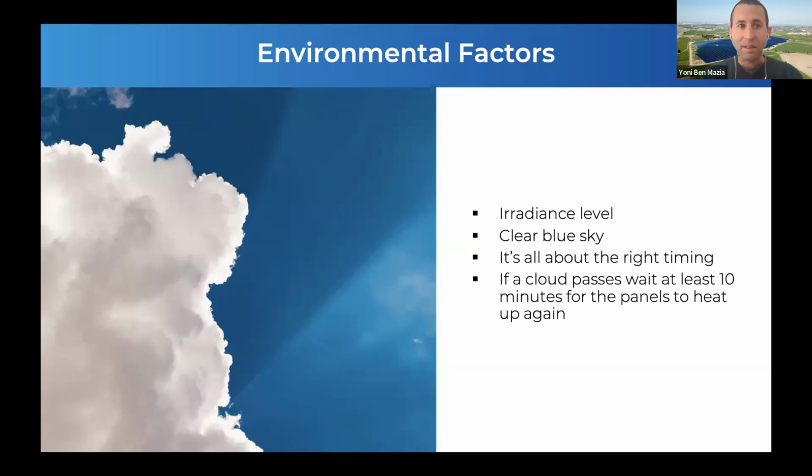And there are some coincidences: the pilot comes to the site, starts to fly, and then a cloud comes in. So usually the instruction is, when we have shade on the system itself, land, wait for the cloud to pass by, wait a few minutes for the modules to start producing again and heat up, and then resume the flight from the point where you stopped. But this is how we usually mitigate.